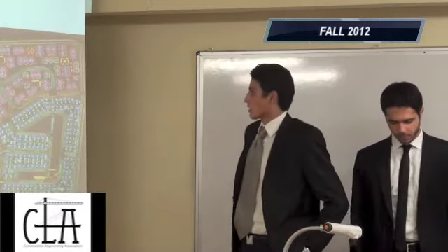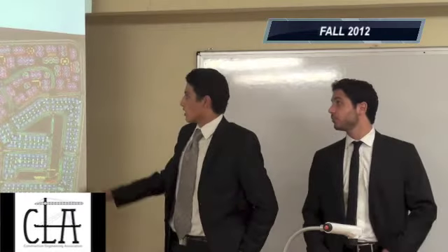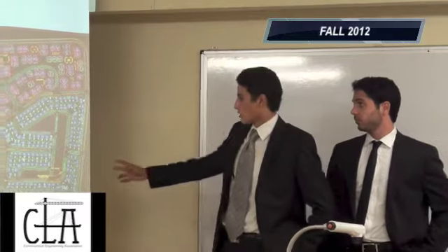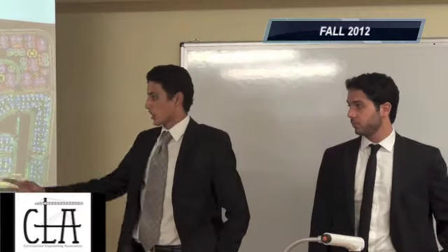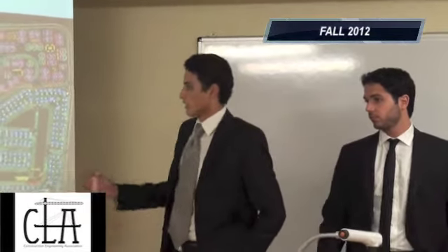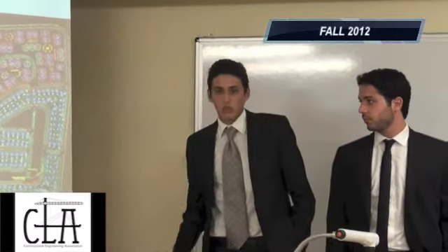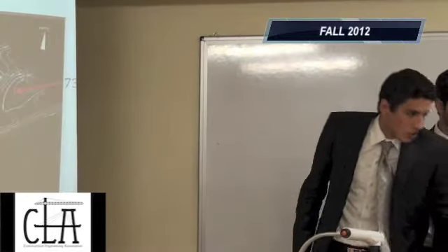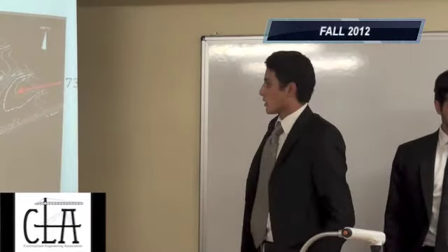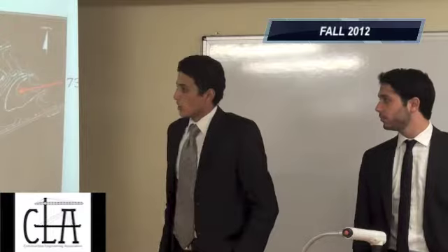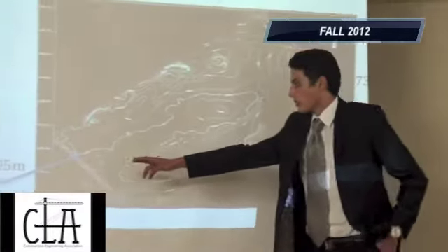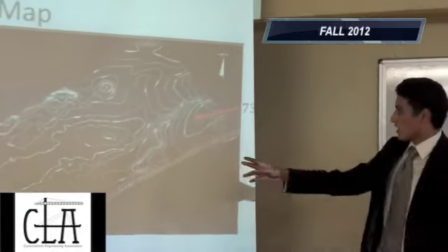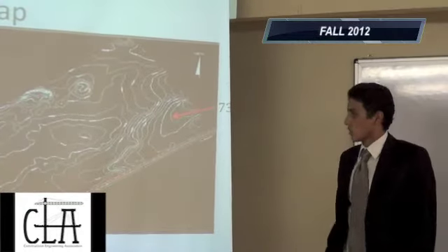This is the plan for the residential complex. These are the plans for the four-story apartment buildings, and these are the plans for the villas. This is a social area including a soccer field and transports, and this should be taken into consideration when calculating the irrigation plan. We've been able to reach the contour map of the site. This is the highest, or most critical, part, at 95 meters elevation above sea level, and the slope decreases until it reaches 73 meters above sea level.